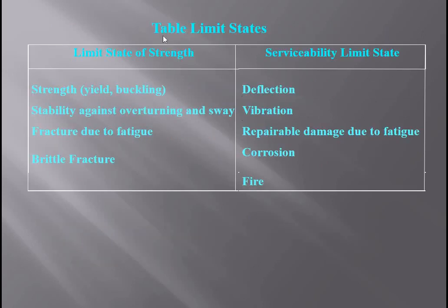These are the limit states of strength and serviceability. For strength: yield and buckling, stability against overturning and sway, fracture due to fatigue, and brittle fracture. The serviceability limit states are deflection, vibration, repairable damage due to fatigue, corrosion, and fire.